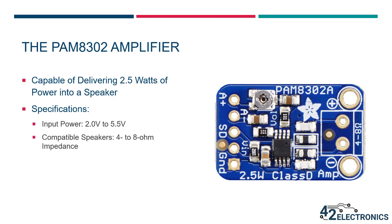The amplifier included in your kit is built around the PAM8302A chipset. It's capable of delivering 2.5 watts of power into a speaker. Let's go through the full specifications for this one. The input power is between 2 volts and 5.5 volts. Compatible speakers are going to have a 4 to 8 ohm impedance. If connecting your amplifier to a speaker other than the one supplied in your kit, you need to ensure the impedance rating is in the 4 to 8 ohm range. Speakers with ratings outside this range can actually damage the amplifier.